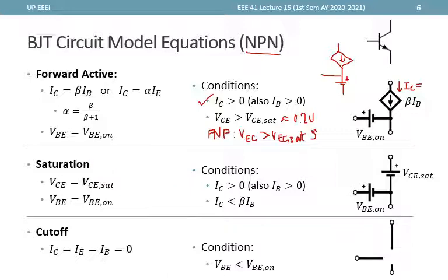So they both act like forward biased diodes. Although take note that this is not 0.7 since this is not VBC but rather VCE. And in terms of our IV curves, in the saturation region, we normally work around this range, and that is approximately at 0.2.